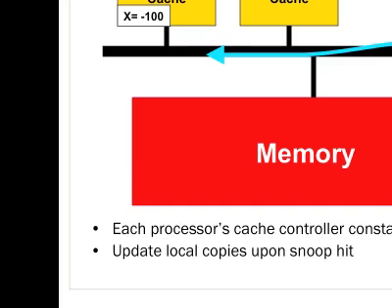So that's why you see this bus transaction. With the snooping, this write-through operation is seen by the cache controller of the first processor. It sees this is a write to this variable X or location X, and the new value is 505.